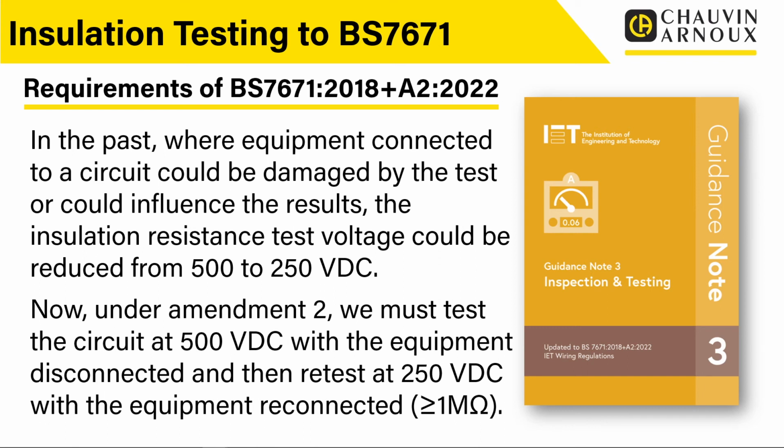So I think there will be arguments that people will use when it comes down to electrical installation condition reports, and there may be limitations, or comments that people make on the test, to say that they weren't able to carry out that test with all the equipment disconnected first. But again, there is a change in the regulations, and it has been done for the right reasons, really, to make sure that people are actually testing at the highest voltage they can. What was happening was people were just choosing, right, I'm just going to test everything at 250 volts because why wouldn't I? It's easier, I'll just do 250 volts, and that was it.